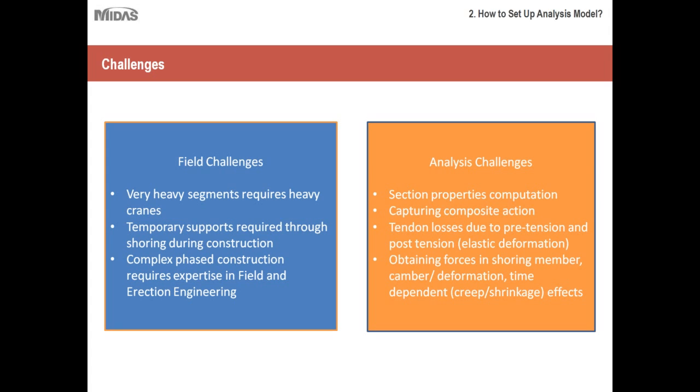So the challenges could be categorized under two main headings. There are some field challenges, and there are some analysis challenges. For field challenges, like I mentioned, the segments are very heavy, so they require heavy cranes. Then you always require temporary supports, and for this you require shoring during the construction work. Then since their construction is pretty complex, they require complex phased construction, for which you really need to have expertise in this field and erection engineering.